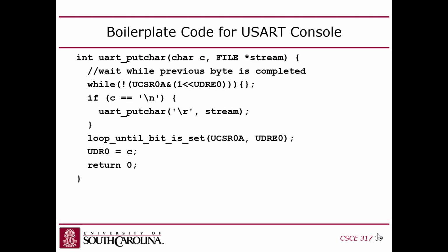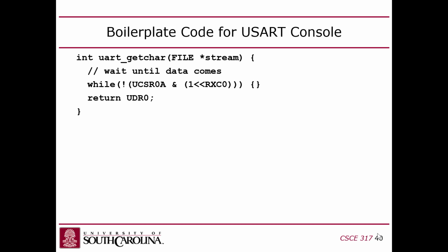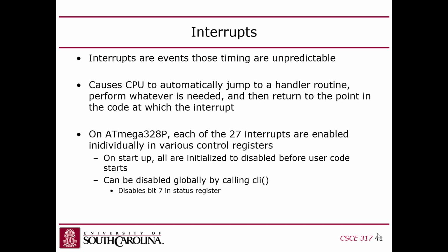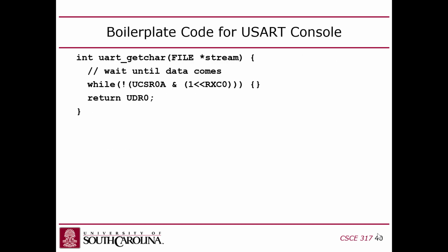This totally ignores that and just assumes you're always reading or writing to the console, because I wanted to keep it simple and not have a bunch of extra stuff. Otherwise, you'd have to have conditional code in here that looks at which stream it is. So there's UART getchar and putchar, and once you have those set up, you can use printf and scanf, and they'll use the hardware UART controller on the chip.